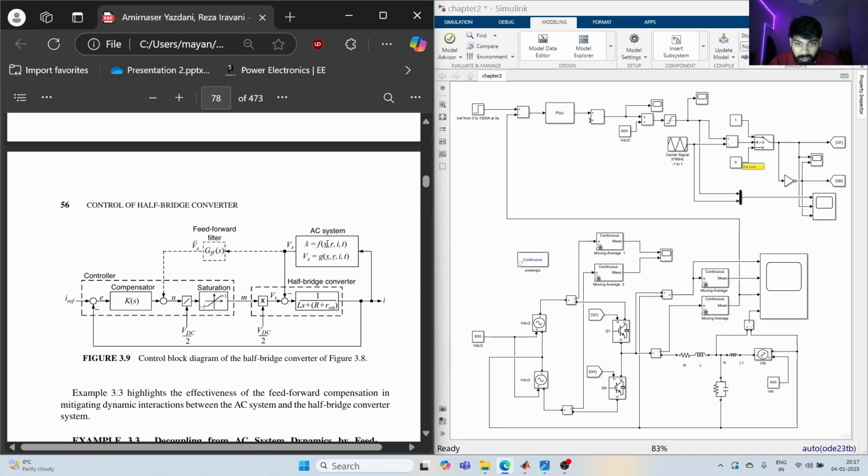With the current that you have, you'll derive a Vs in a control format, carrying all the information of the characteristics of the AC system, and that will be added after a feed forward filter. Obviously it will add to the output of our compensator like we were doing before, as is done in the case of a feed forward compensation.